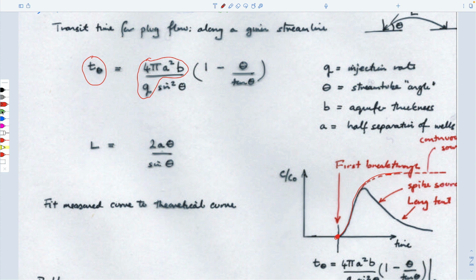I suppose if we thought that on top of that perfect plug flow it had some mechanical dispersion, then our curve would look like this on top of it. And so this is with no dispersion. So it's not like our previous ones where with no dispersion we've had a really sharp front that's canted over like this. Here we have a flaky front that's due to the effects of the flow regime.